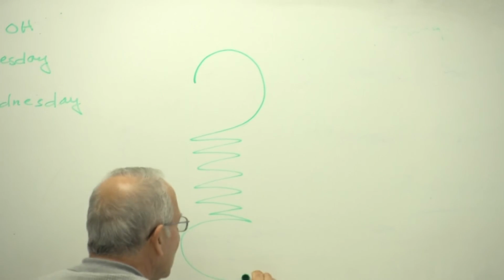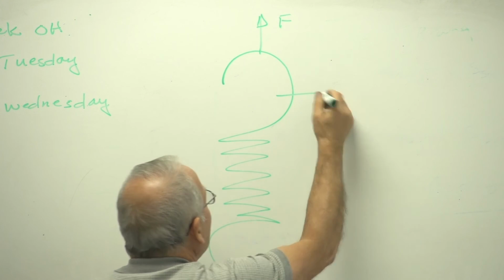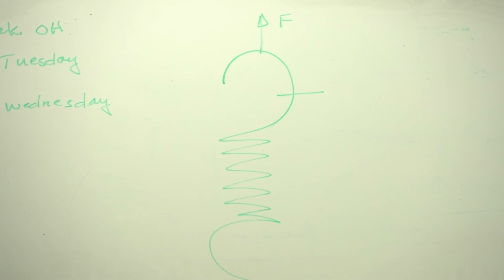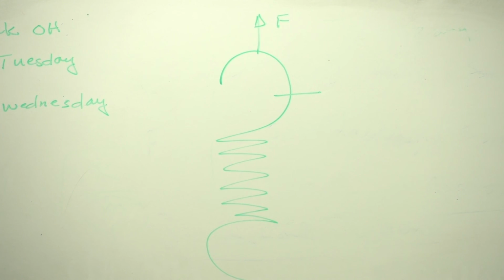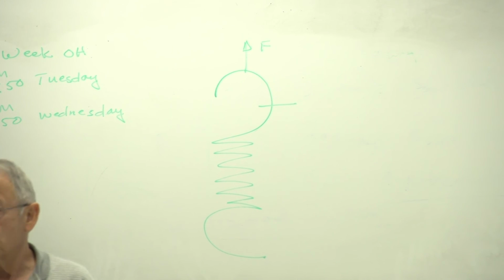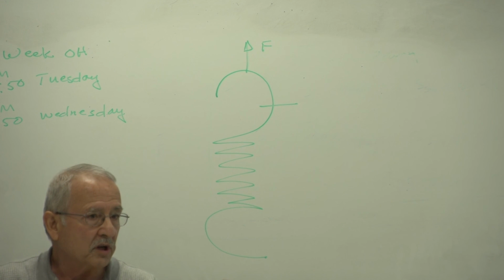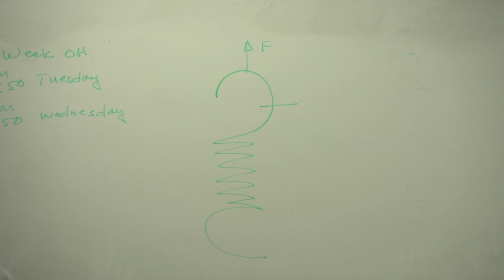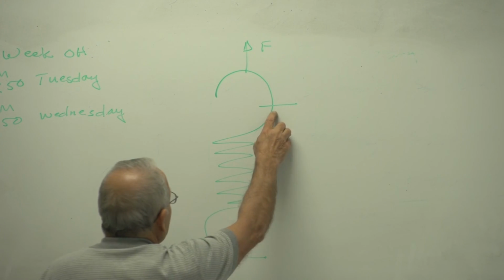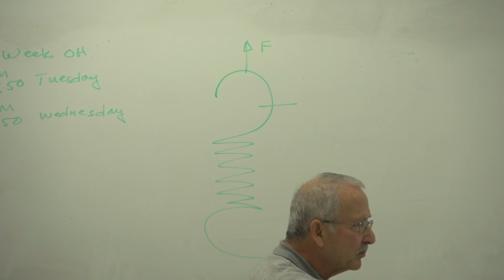schematically, if this is your tension spring, and you apply a load here, F, well, that section is under bending. So you need to worry about the bending of that section as well. It is also curved, so it's a curved beam. And we generally use a stress concentration factor to take care of the curvature, and this is no exception, and we'll do that. So this creates bending here. What does this other curvature down in here create?